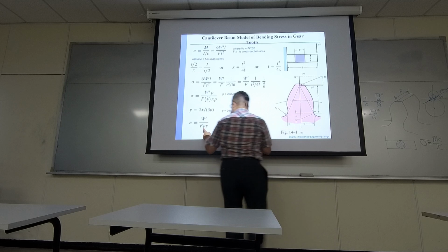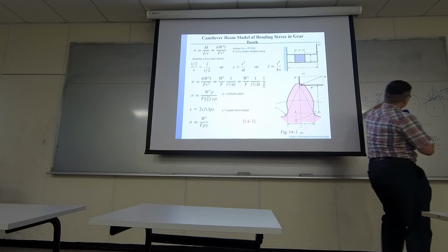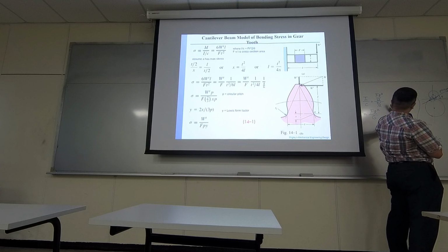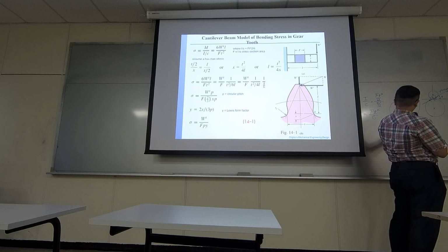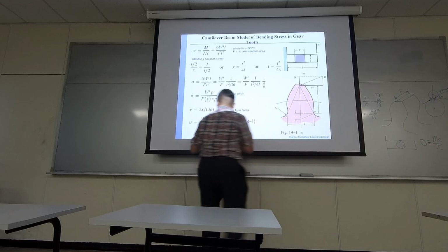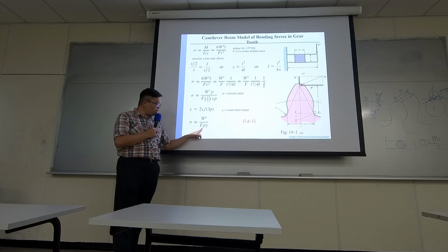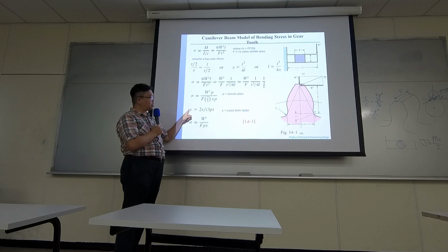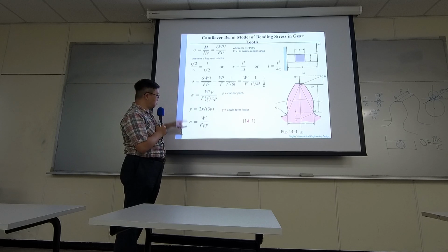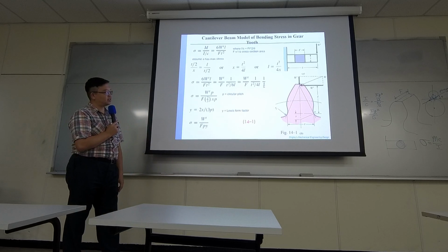But when you multiply, it's like you're trying to compute the stress area. You need to compute some dimension in this direction. So over here, you basically multiply the circular pitch times this dimensionless factor y. And by derivation, it tells you that's basically the same stress.